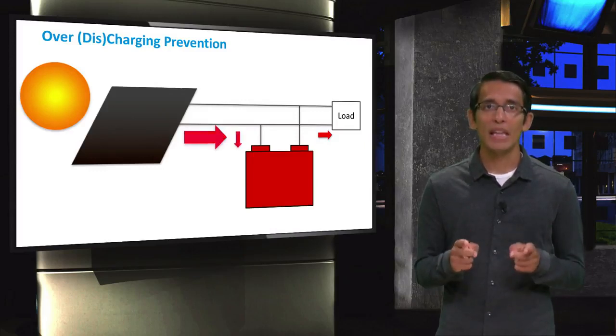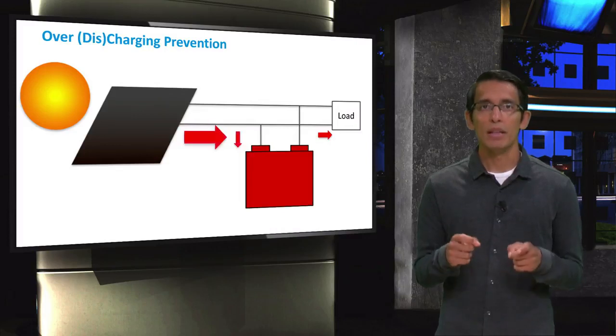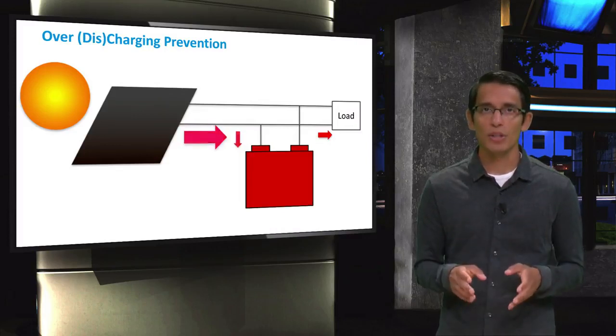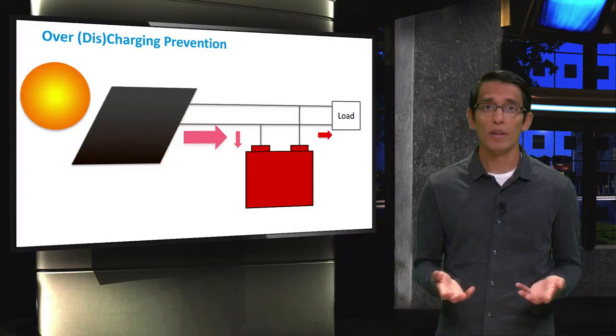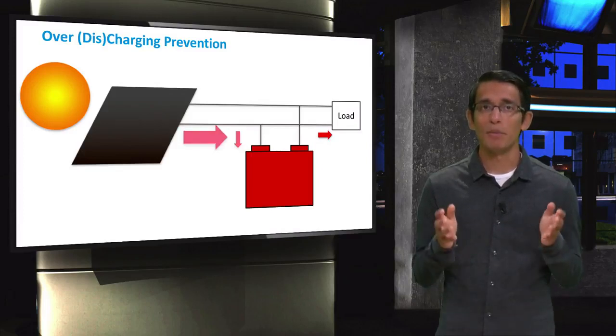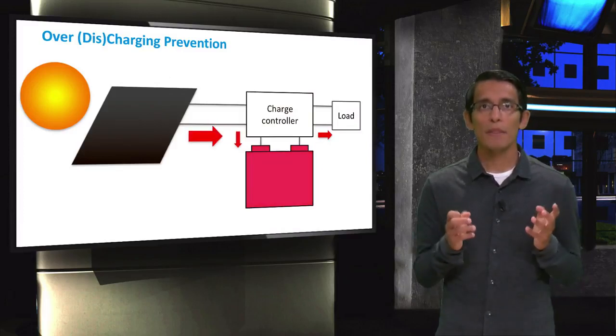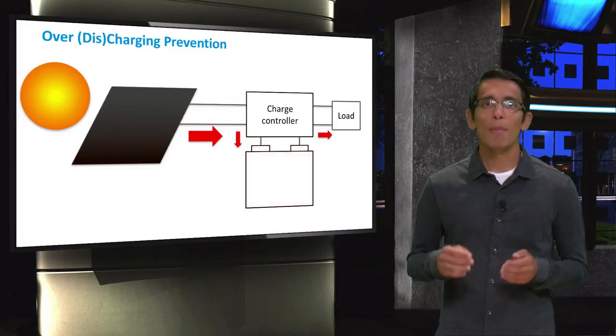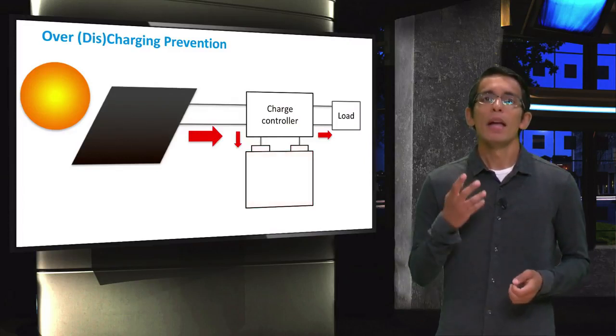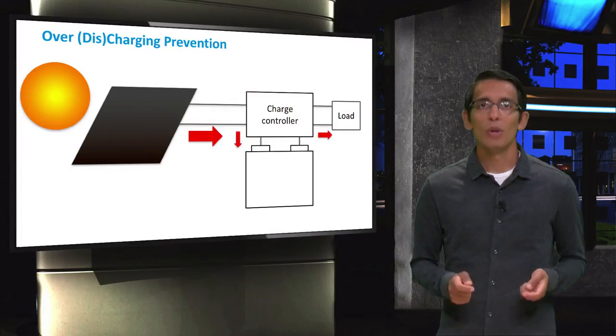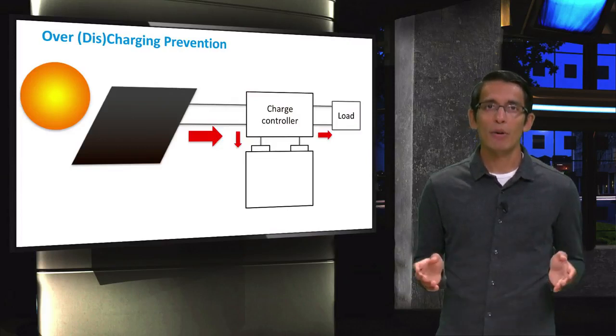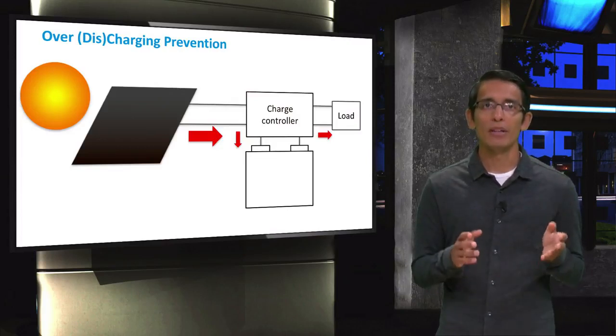Overcharging the battery has a negative effect on its performance. It leads to several problems like gas formation, capacity loss, or overheating, thereby reducing the lifetime of the battery. But with the help of a charge controller, this problem is avoided altogether. Here the charge controller plays a vital role in decoupling the PV array from the battery, thus stopping the battery from being charged any further.